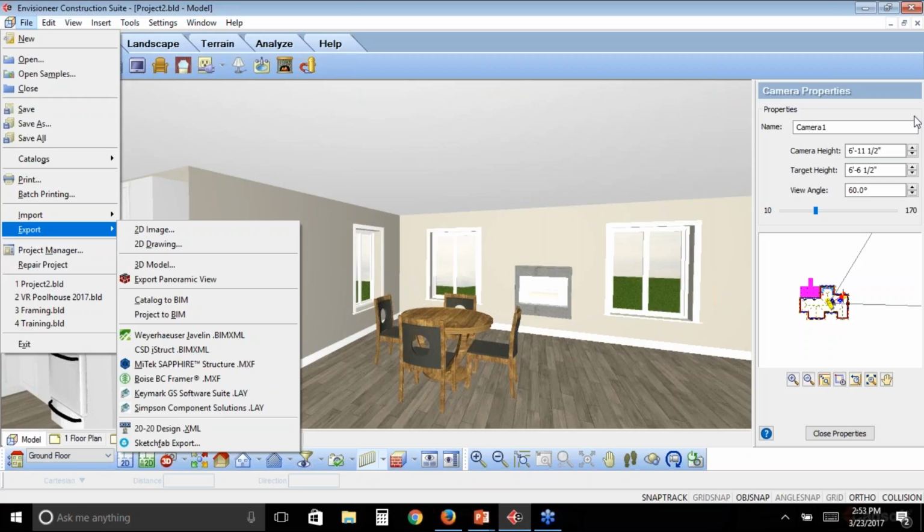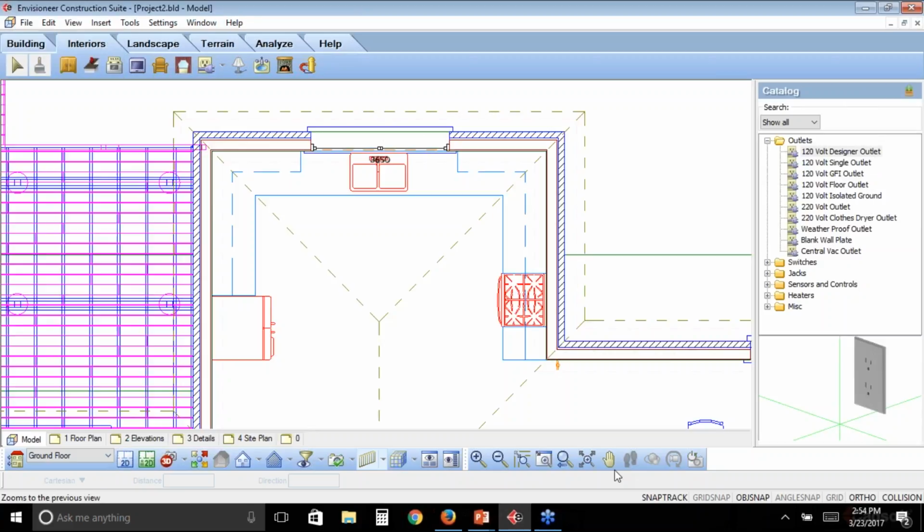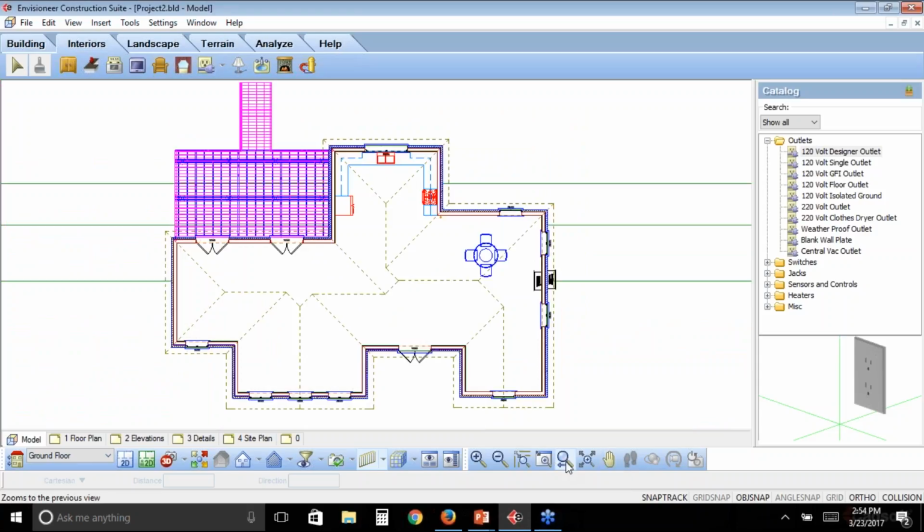Next question. When placing an element out of the fireplace, will we be able to immediately know potential conflicts? You'll be able to see them. So we have different flags and different things that will tell you that it can and cannot do something. As an example, I'm going to put it back down into our 2D view. So the question is, what about conflict control? With all of our objects, we have what we call collision control.